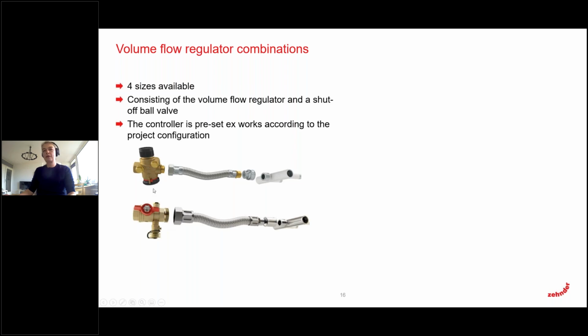Usually we put the flow regulator itself in the return line of the panel, just because in heating applications there the temperature is a little bit lower, but this is more or less a historical decision.